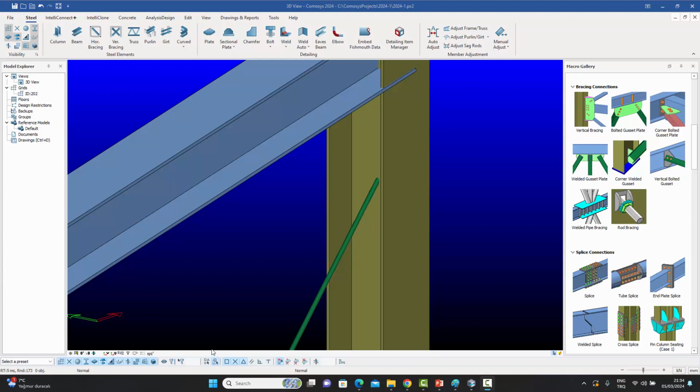Now let's consider this situation. This is the fourth macro which we've developed for you in this version. Usually, whenever we have significant seismic forces or significant wind forces, you never do something like this. You don't use these flimsy rod profiles as your bracing. But when your loads are really low and all you need to do is just make the structure stable, take a little bit of load, then it is common practice to use these rods as bracings. And in those cases, obviously, you want a simple connection, and some standardized equipment is also used.